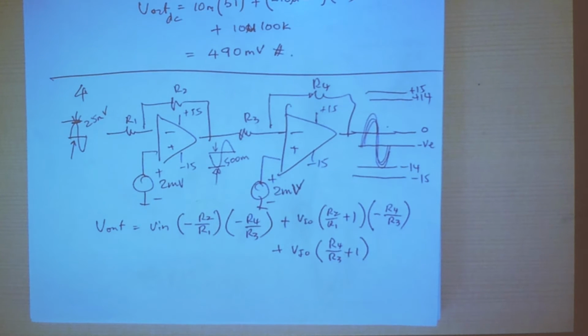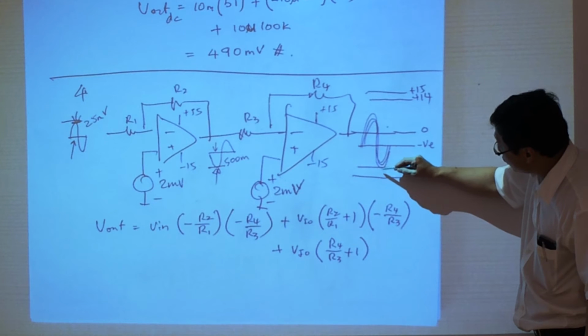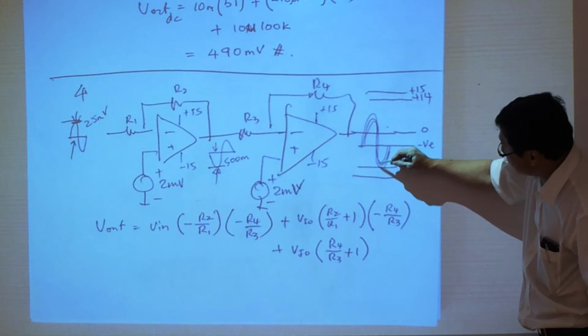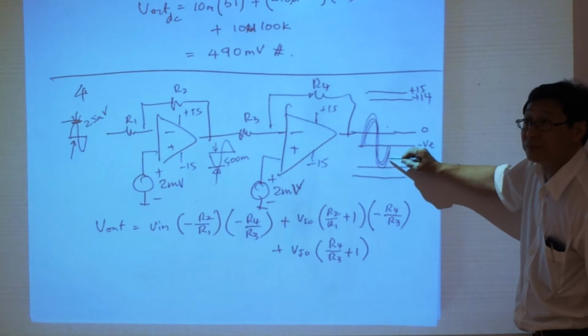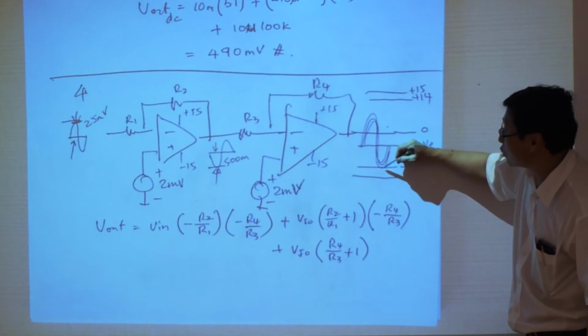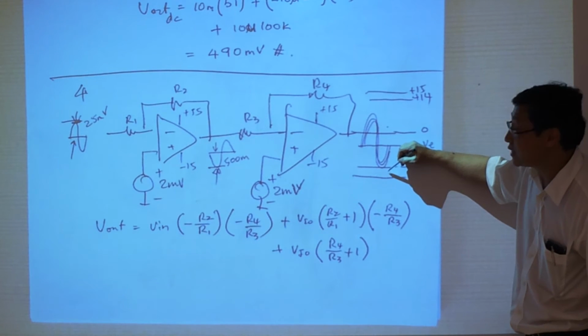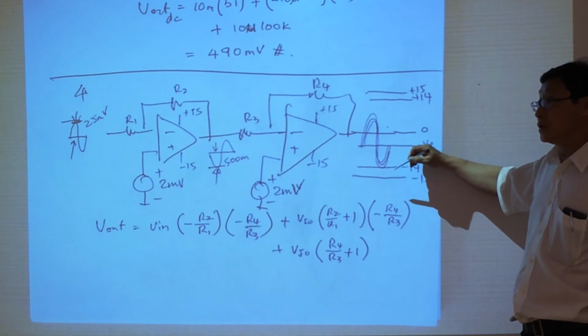Further increase in the gain R4 and R5 is going to increase the output signal further. And with any increase, the output will not be able to go across minus 14, but instead it will be flattened out. It will be clipped. Right? Therefore, it will go through a nonlinear region, and therefore, this is not what we want.